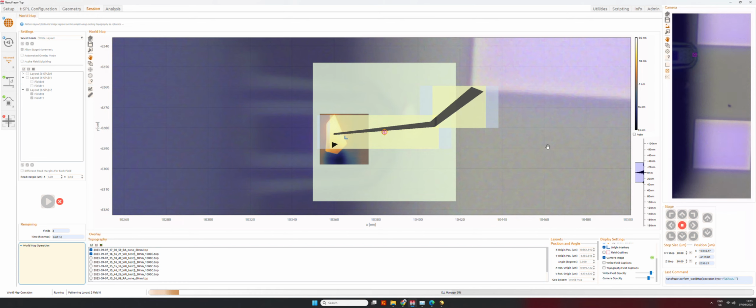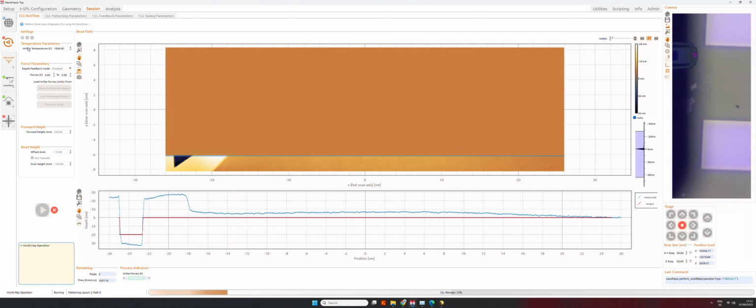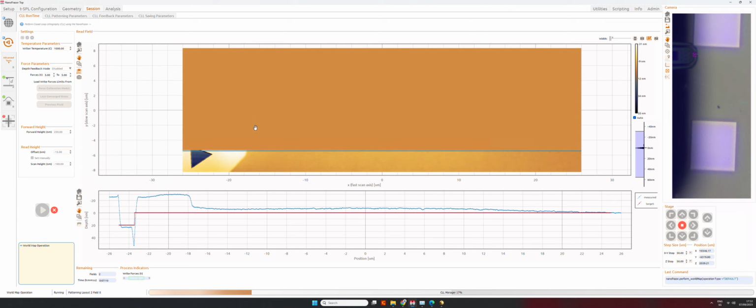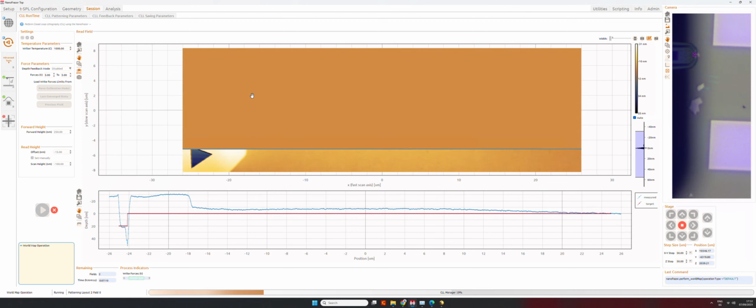Here it's not very crucial because we don't have a very high resolution alignment, but it's something that we need to keep in mind in case you want to avoid the error in alignment of fields that is introduced with moving with the coarse stage, and we're talking about 100 nanometers pretty much, and it's an error that's not always constant, so we cannot have a fixed number for that.